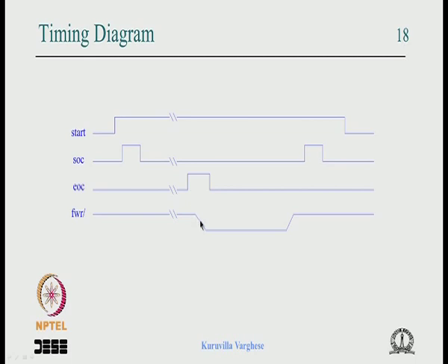to one state and make it low. Now if you know the clock period of the controller, suppose it is 5 nanoseconds and you need a 25 nanosecond width for the FIFO write, then one thing to do is to first come to a state where the FIFO write is low, transit to the next state where FIFO write is low, and go on doing that for 5 clock periods or 5 states, then you will get a clean pulse. But this is quite cumbersome.